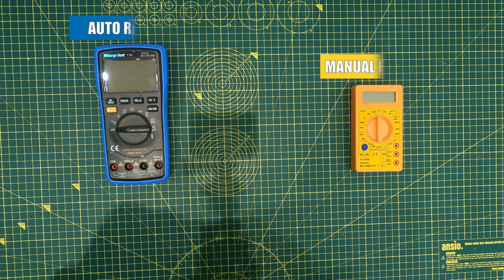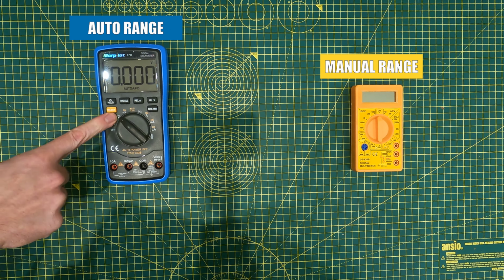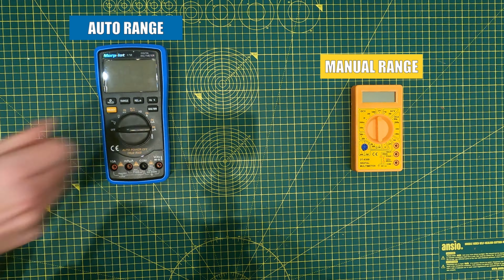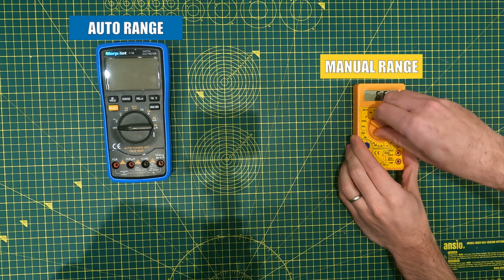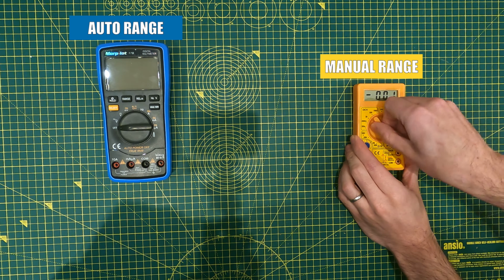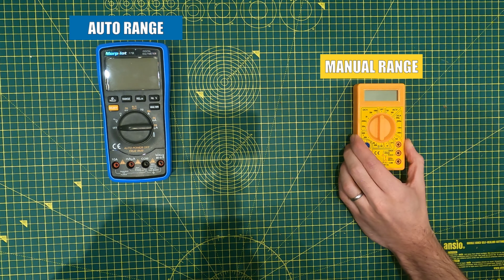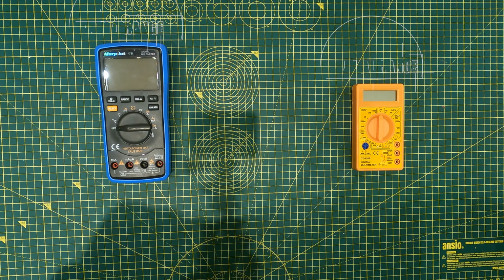So you have the auto range multimeter, where you just select the feature that you want and it'll automatically find the range and value for you. Then you have the manual ranging multimeter, where you have to select a predetermined value, and then that will allow you to take the measurement. I'll go into more detail with this later on in the video. Let's go ahead now and take a look at the auto ranging multimeter first.